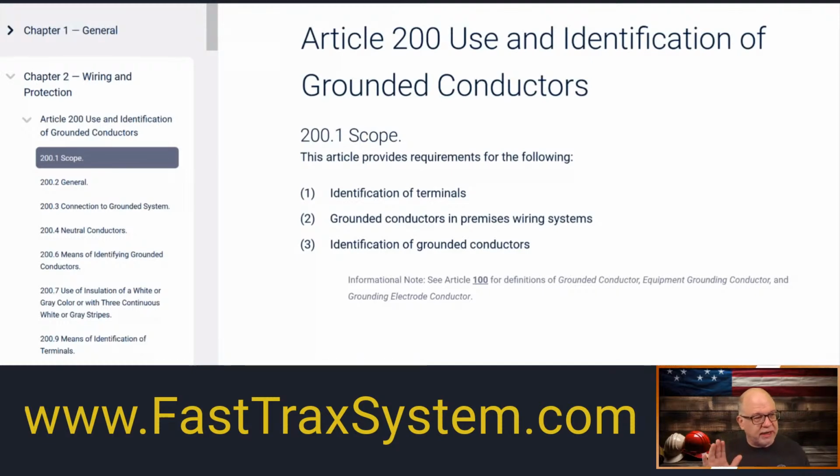Now, the exception to this rule for grounded conductors is, for example, on service entrance cable, where it would be helical and it's serving a duty as being the grounded conductor. Then it's not color coded because it is bare and it's inside of a cable assembly, right? Or you could have a service drop where it is a bare messenger supported with the steel core. It's ACSR, for example, aluminum conductor with a steel reinforced core. That is a support that typically will be bare. But once we get past the service, most of the time we're going to have insulated grounded conductors, and we have color coding. Again, the exception to that rule is cable assemblies that allow you to have the bare in it, like an SEU product, that type of thing.